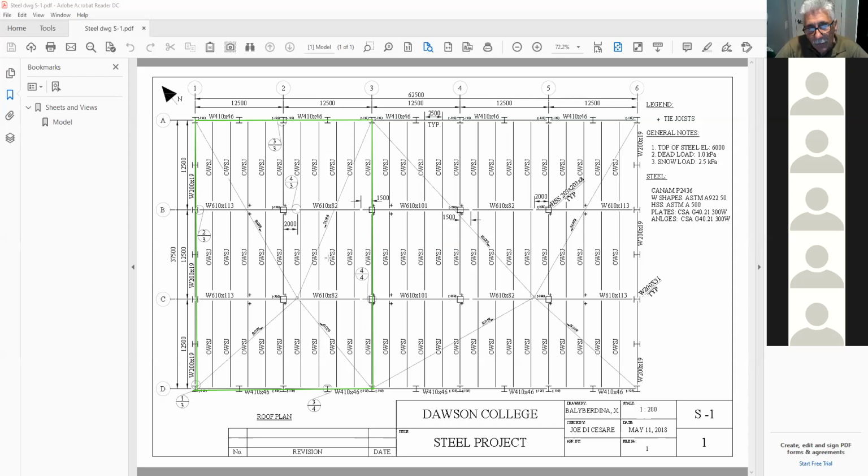Now, you shouldn't exceed 7% because on a city sidewalk, if you exceed 7% and it gets icy, there's a danger of slipping. So there are minimums and maximums that you should keep in mind, depending on the surfaces and where they are. I don't know which course they should teach about sloping, but I learned this, God knows where. I learned about my minimum 2%. I learned about my maximum.